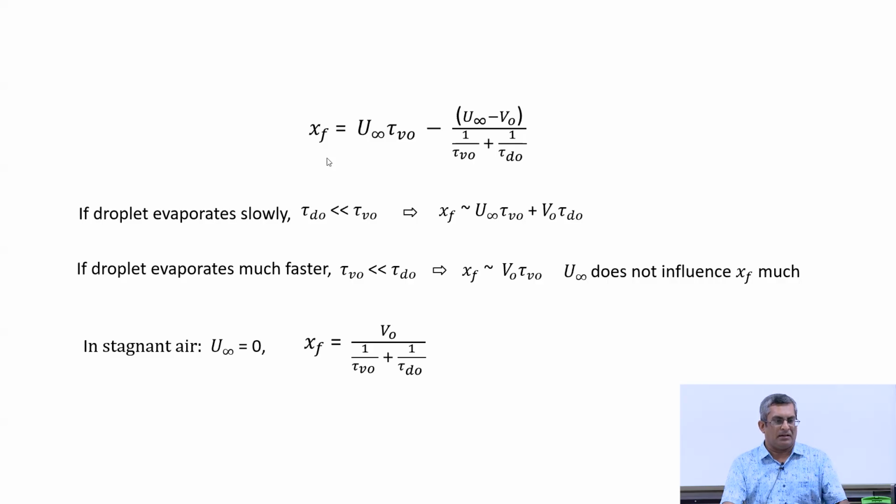By integrating the equations from d equal to d naught, that is the initial size, to 0 when the particle evaporates completely, we could find the distance traveled by the particle. In this case, this depends on the vaporization time scale obtained from the d square law and the particle relaxation time, where both are defined based on the initial particle size.